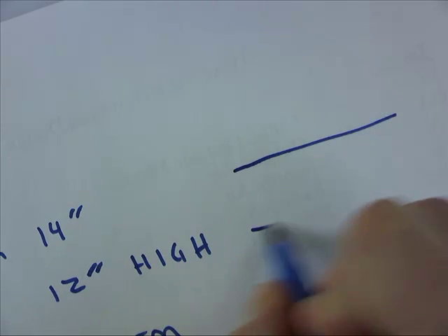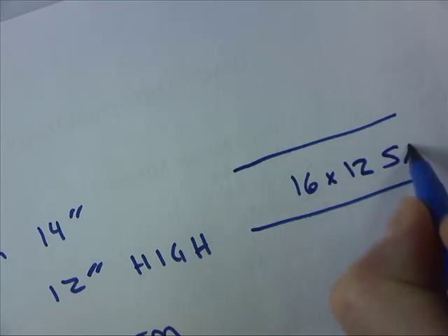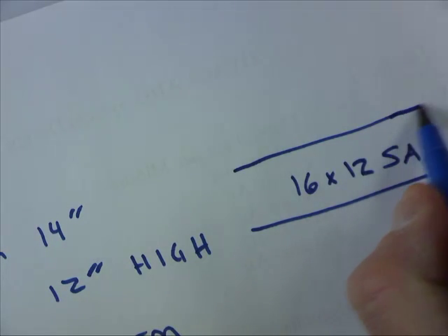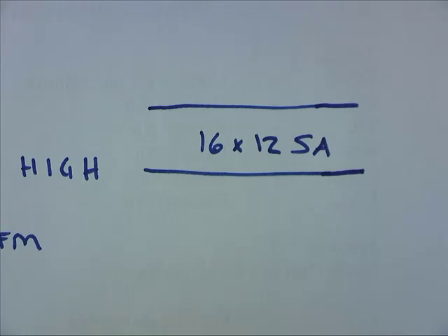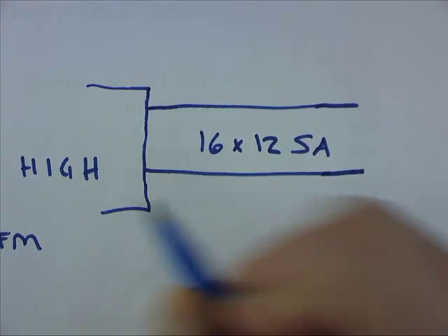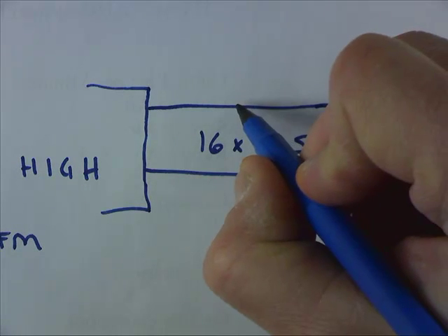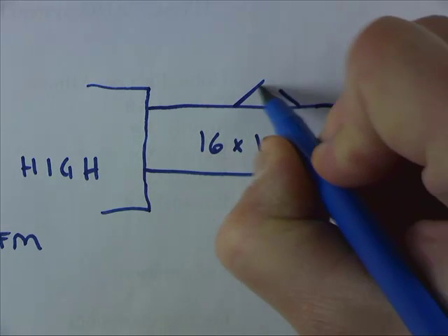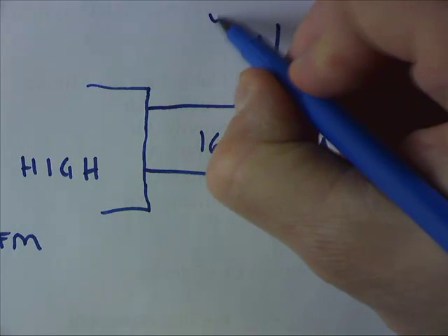And we'll say that's coming from the unit. Let's say I have a branch. I'm not going to worry too much about that. I have a branch that dumps off 400. What's going to be left right here, at this point, is 1,000 CFM.